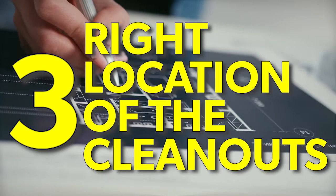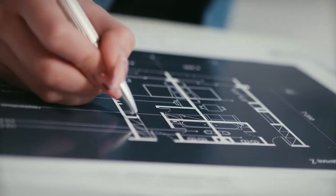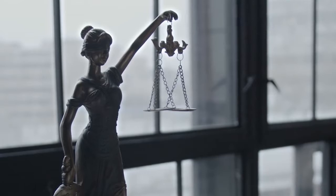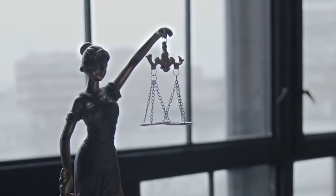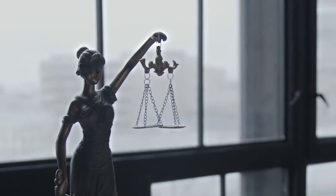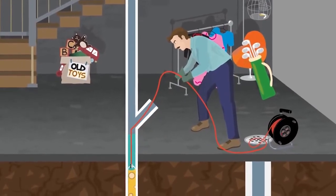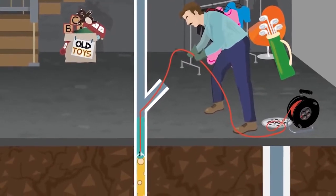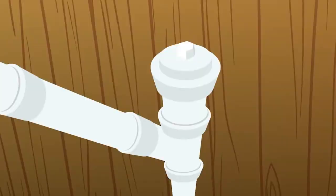3. Right location of the cleanouts. The location of cleanout must be indicated in the plan. It should be sized equal to the diameter of the waste pipe where it is to be connected to avoid interference in the rodding or cleaning process. Also, it must be readily accessible to the plumber in case of wasteline stoppage.